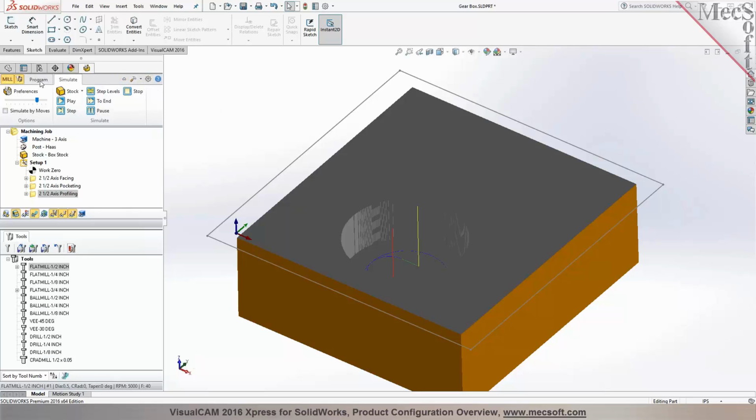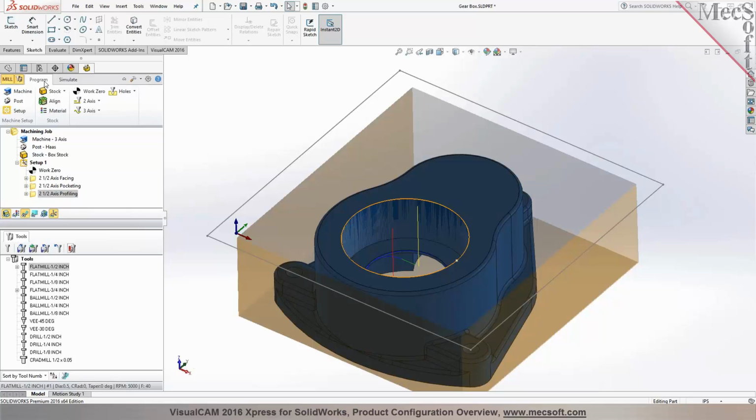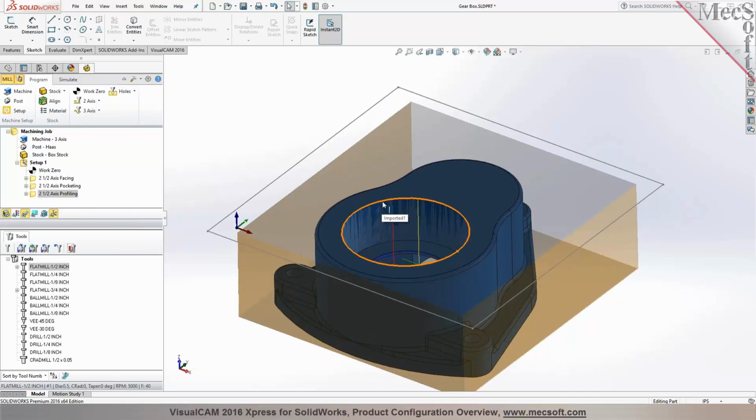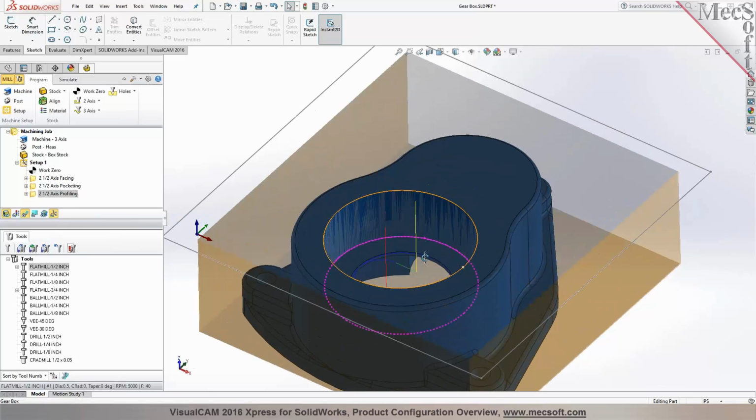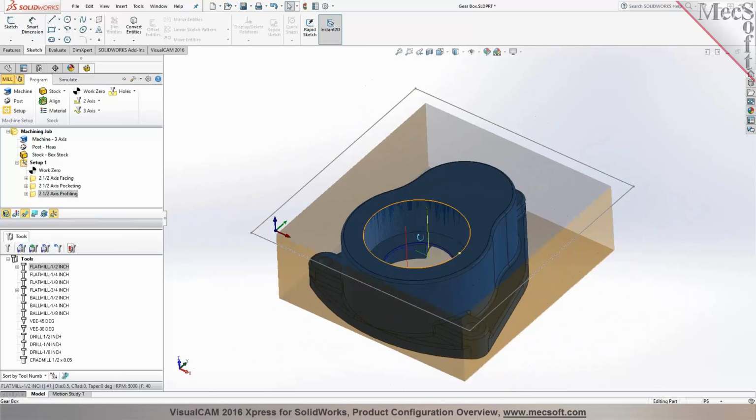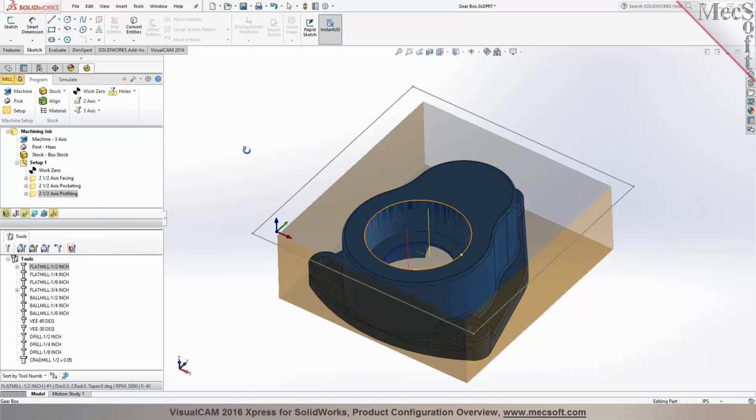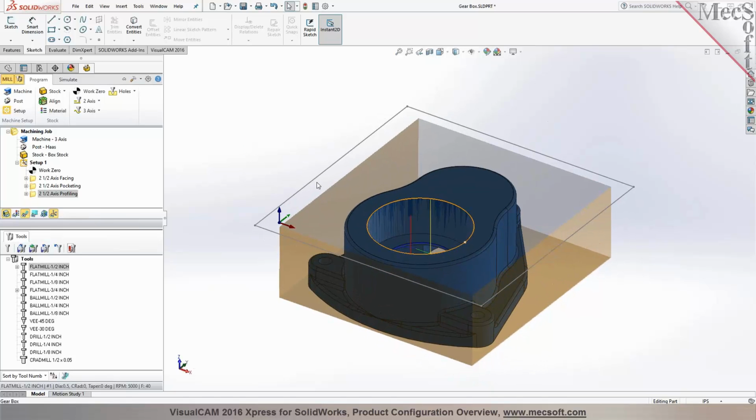So there's your toolpath. Now, if the geometry you select is an arc or a circle, then the toolpath arcs are automatically being fit to the toolpath, as you notice in here. So the arcs are represented in dark blue and the linear motions in cyan color. Now we've got the inside features programmed. The next step we want to do is program the outside features.